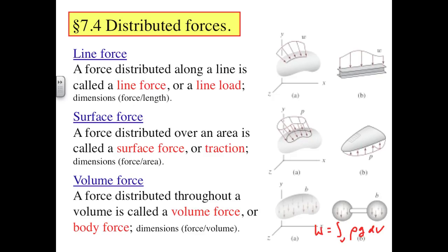These gravitational loads are perpendicular to the long axis of the crossbeam and are sometimes referred to as lateral as opposed to axial loads. The interesting part of a crossbeam's behavior is its lateral deformation along its length and the stress that induces in the beam. Instead of working with weight as a body load, we multiply the body load by the cross-sectional area of the beam to obtain a line load.